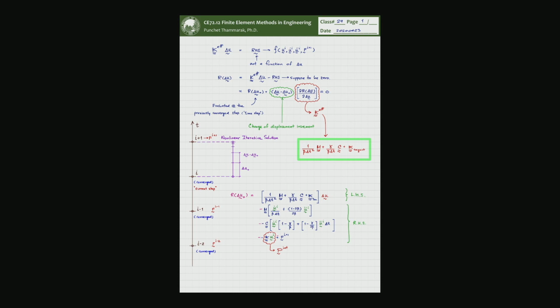So that depends from problem to problem. As long as the stiffness of the overall system is still okay, then the analysis still continues until you get to the real ultimate point of the structure. It is not the local point, it is the structure's ultimate point, and that's where it is going to stop if you don't augment the code with a technique that stabilizes this issue.